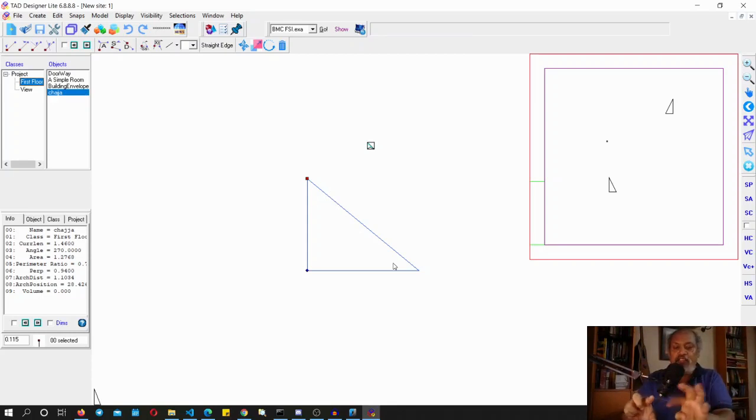And this is a nice visualization because you remove that pin, it becomes a triangle. If you remove this, these two lines actually will become one. So if I press Control Backspace again, it looks as if I have drawn a line. Actually, it's not a line. It's still a closed shape, excepting both the lines are coincident, one on top of the other, because it's mathematically very precise. So the moment that particular vertex has disappeared, it collapsed into a line. If you delete that vertex also, it will become a point, which I don't want to do because it's pointless. So what I now do is that I'll undo these shapes.